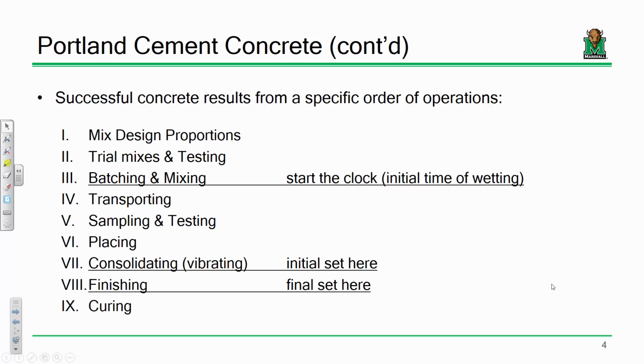They're always doing regular QA, QC, so they're doing this throughout their business operations. But once you've got that taken care of, get everything weighed and batched together, get it all proportioned, then begin mixing. The clock starts, because once you get water in contact with that cementitious material, that's when you have to start timing things out, getting ready for